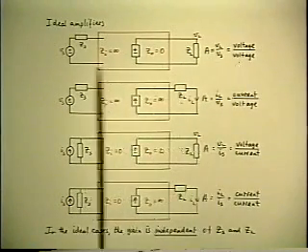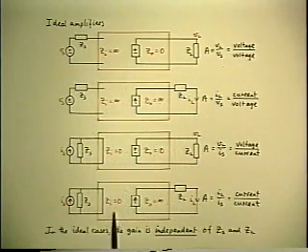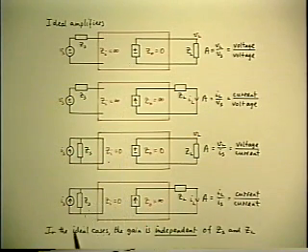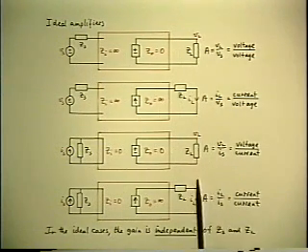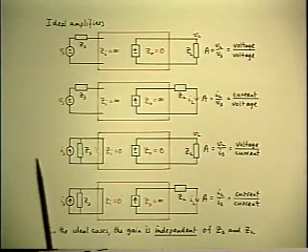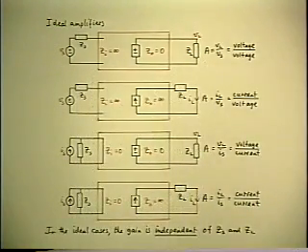So let's start with defining what an ideal amplifier is. In terms of electronic signals, there are four possible combinations. You could have a voltage or current source, and you can have a voltage or current as an output quantity. So there are four combinations of those. The one we normally think of is the voltage-to-voltage amplifier. So what is an ideal voltage-to-voltage amplifier? It's one whose gain could be written on a spec sheet that is independent of the terminations that someone else may put on it.